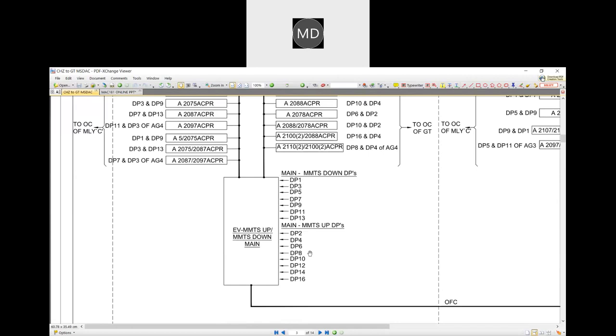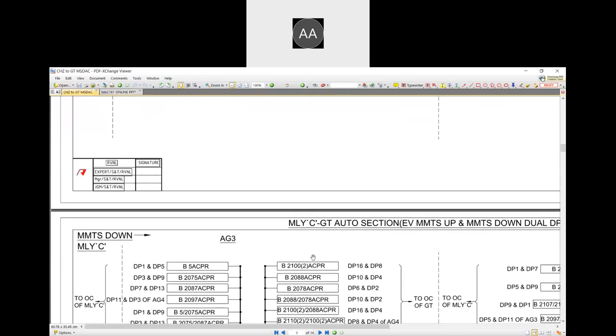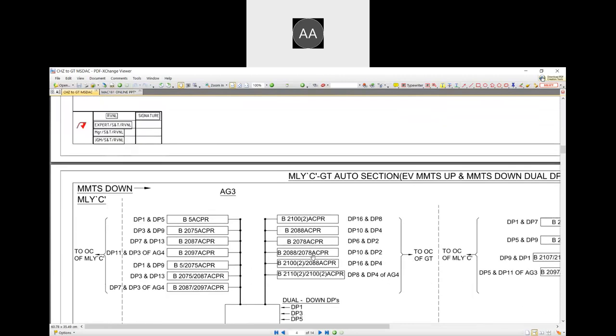If you provide a power supply near the DP, the communication we can carry out up to 15 kilometers from the evaluator to the DP, if it is possible to provide DP power supply locally. Otherwise, the possible communication is 3 kilometers.